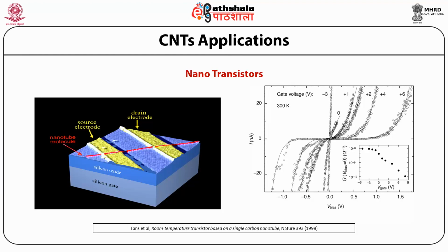The key to being able to reduce the transistor to such a small size is the use of a carbon nanotube as the channel, placed on silicon. The nanotube is only 1 nanometer thick. Such thickness offers a significant advantage in electrostatics, so that it is possible to reduce the device gate length to 10 nanometer without seeing the device performance adversely affected by short channel effect. An additional benefit of the nanotube is that the electrons travel much faster, which contributes to a higher level of device performance.